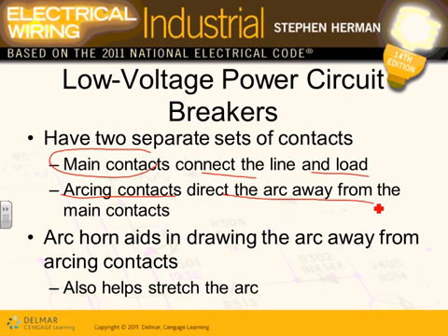So when it comes to circuit breaker design, guys, I can't emphasize this enough. It's all about getting rid of the arc safely. So they add different contacts to get rid of the arc, so you don't burn the contacts that are carrying the current under normal condition.